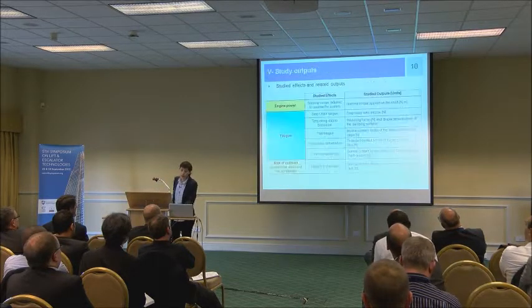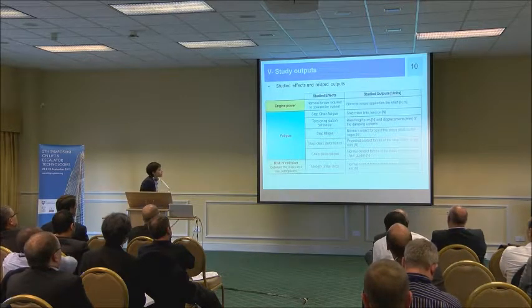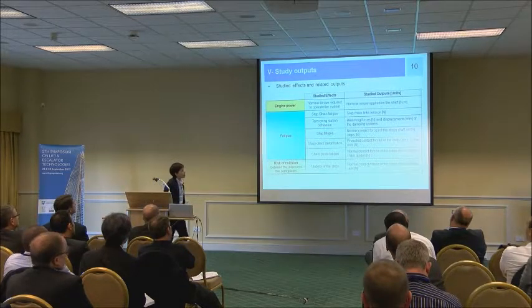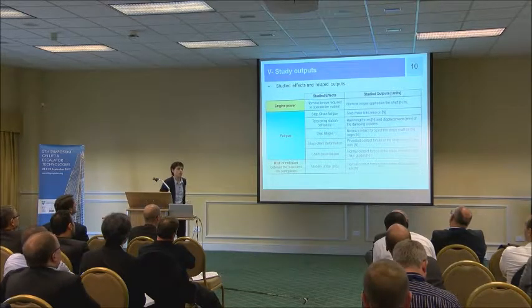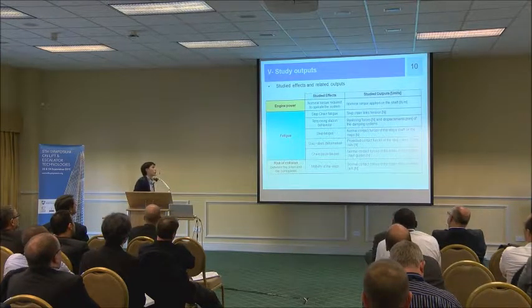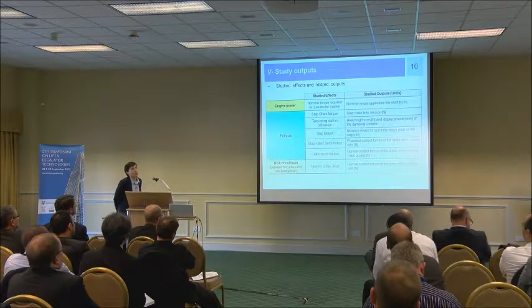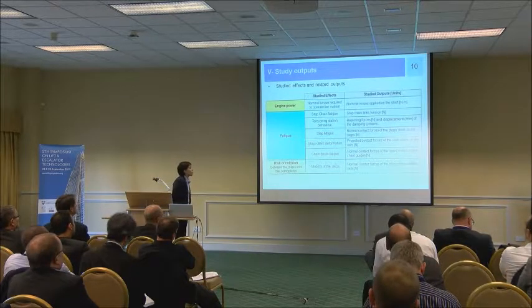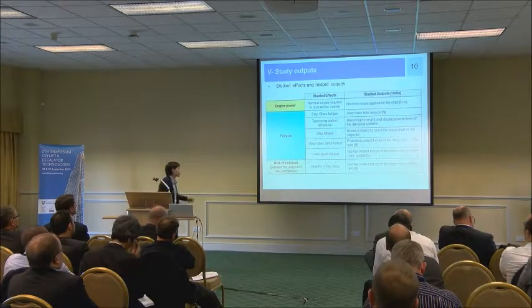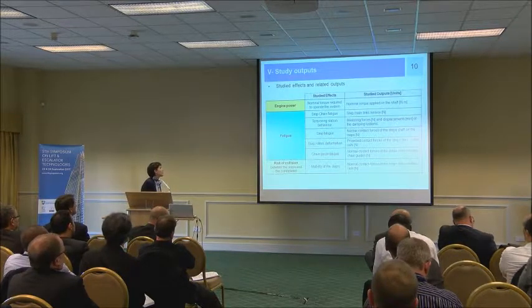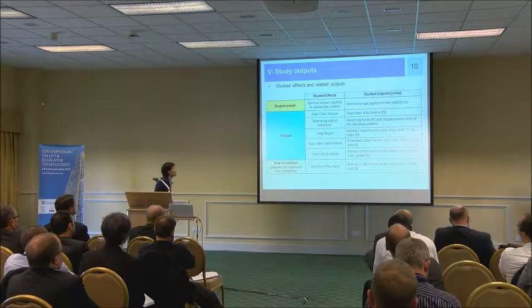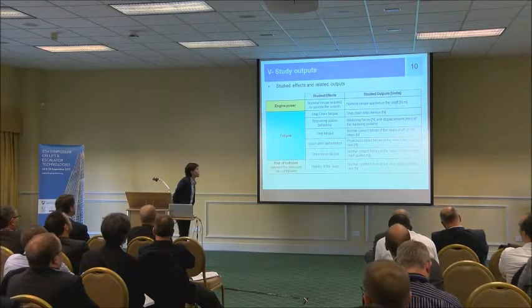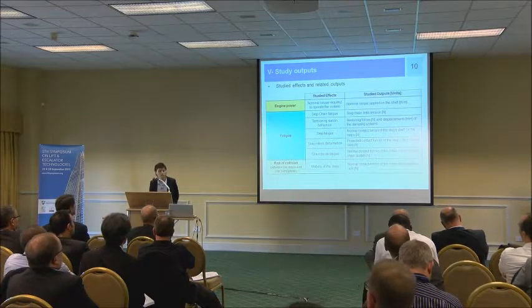So this table requires 27 simulation runs. At each of these runs, we recorded a certain number of outputs, which we selected in accordance with what we wanted to study. So we focused on 3 different aspects. First of all, of course, the risk of collision between the steps and the comb plate, but also the engine power required to operate the system, and the step band component fatigue.